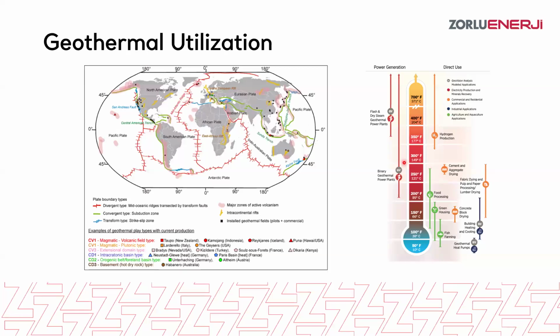Okay, but for the lower regions, the water vapor has energy that cannot efficiently be converted to electricity in a standard steam turbine. In this section, you are using a fluid which has a lower boiling point that could create much more powerful steam or vapor in the lowest temperature regions. That's why we are using a binary fluid to produce electricity from those systems.